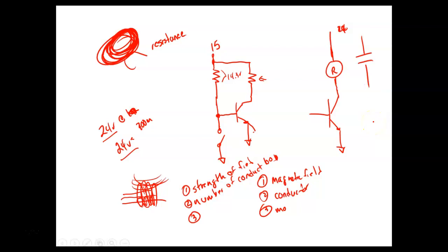But when we turn the transistor off, that magnetic field collapses down into all those turns of wire, and it creates an electromotive force that is extremely high. We'll do a neon bulb that takes about 90 volts to turn it on. I'll charge that coil up on 12 volts, then discharge it, and that neon light bulb will come on, which means that when that coil discharged, it discharged over 90 volts.